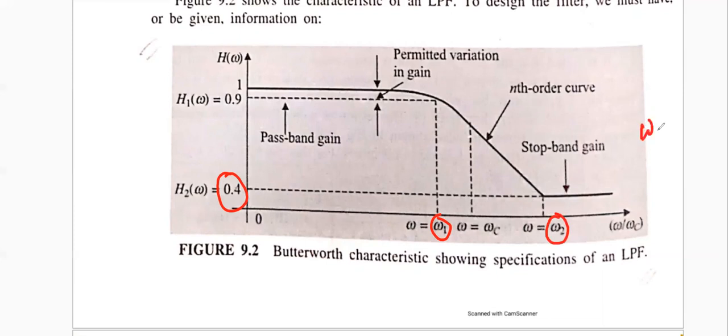What about the cutoff frequency? The cutoff frequency will not be given for the Butterworth filter. It will be calculated automatically by using the order of the filter. For different orders of the filter, we have a different cutoff frequency.